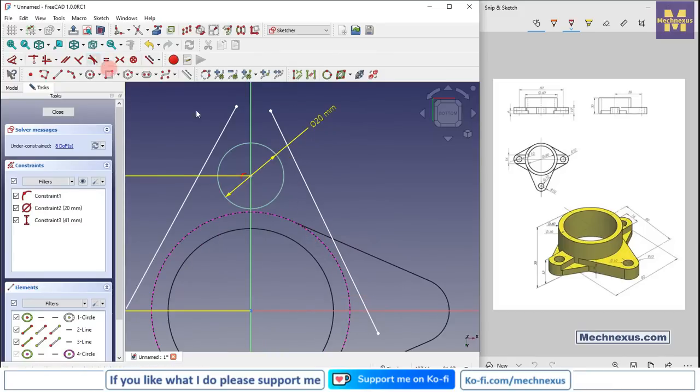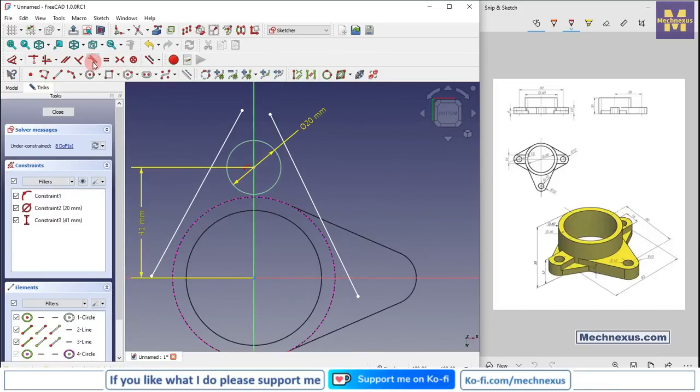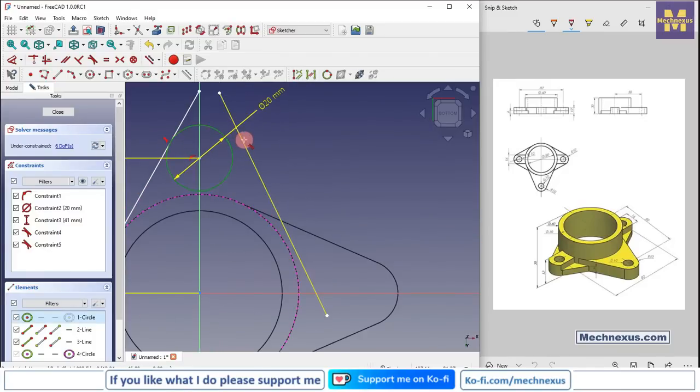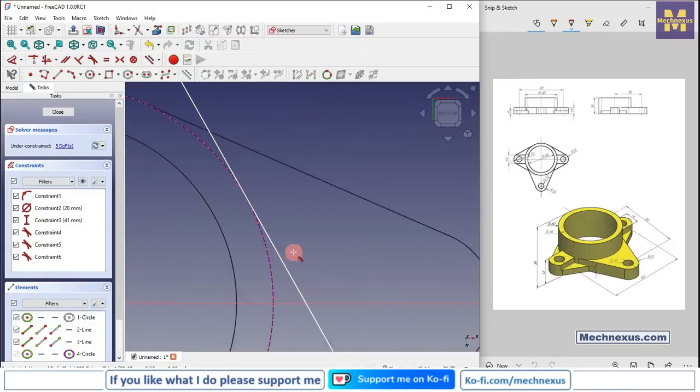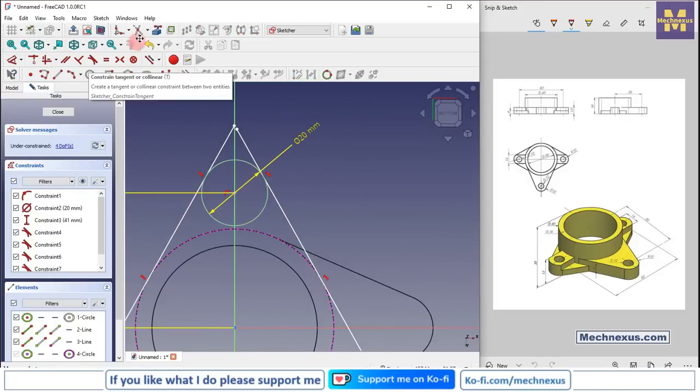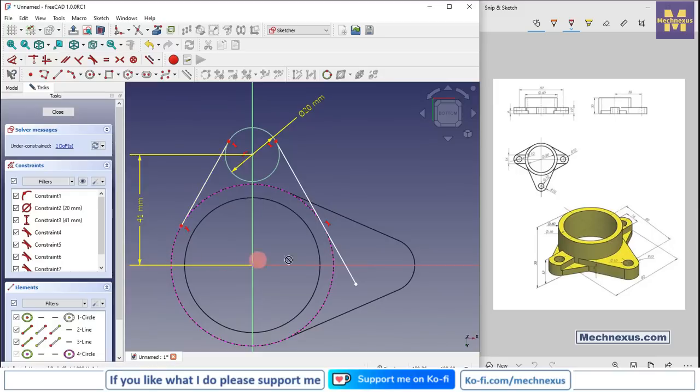Now click on the tangency, select this and this, and add a tangent. Select this and this, add a tangent. Similarly this and this, select this and this and add a tangent. Now we will use the trim tool to trim the unnecessary geometry. Select it, trim it, and also trim it.